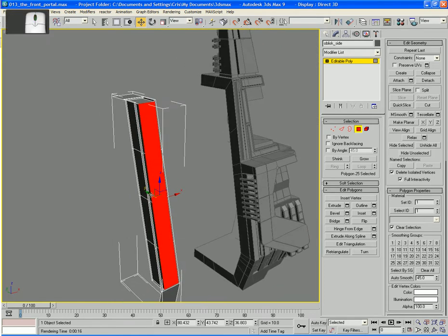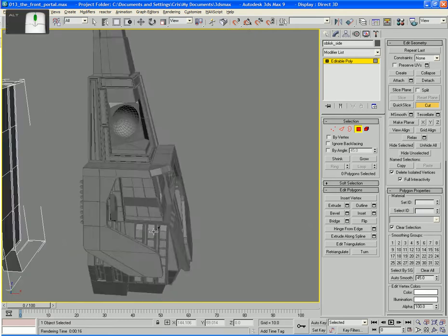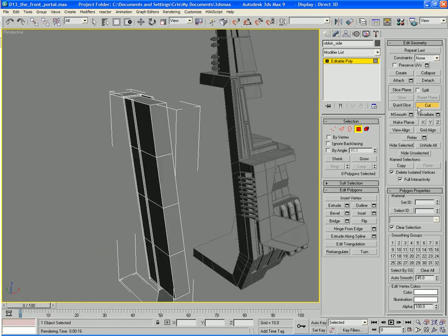Okay, now before I go any further, I'm going to bring this right forward, and now I'll do my cuts. You'll notice the cursor's changing shape when I get to these points here, just so that we know where the vert on the other side is. Useful little feature of cut, that is. Okay, now let's push these back in.